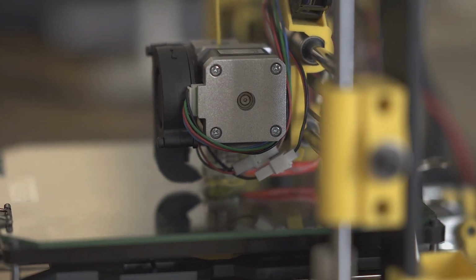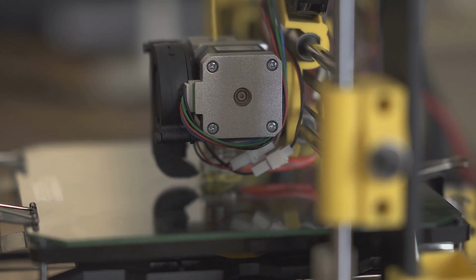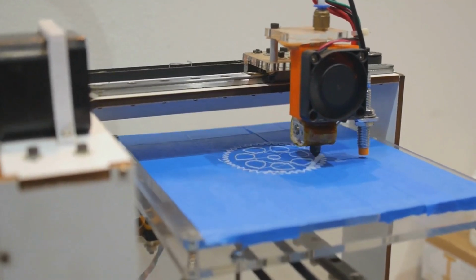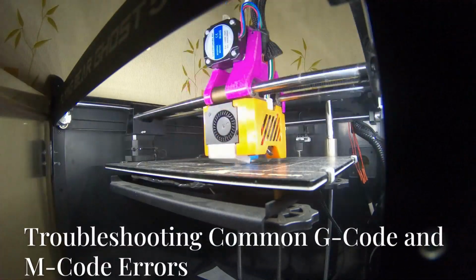M109, Set Extruder Temperature and Wait. This command sets the target extruder temperature and waits for it to be reached before proceeding to the next command. This is useful to ensure the extruder is at the correct temperature before starting to print. By understanding these M-code commands, you can fine-tune your printing temperature, control the cooling fan, and ultimately achieve higher quality prints.